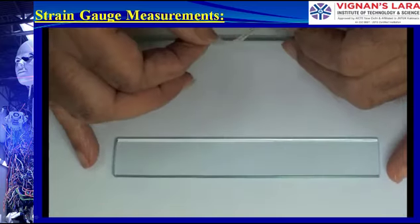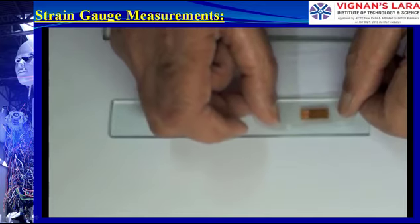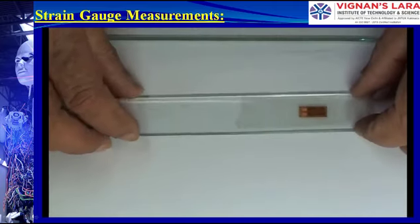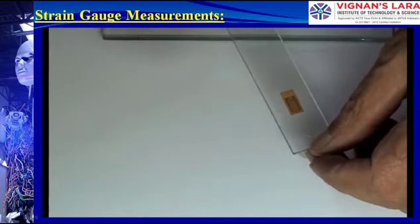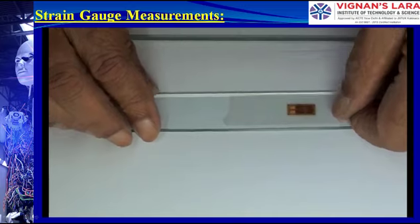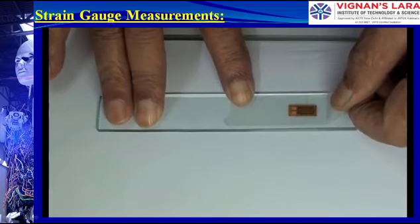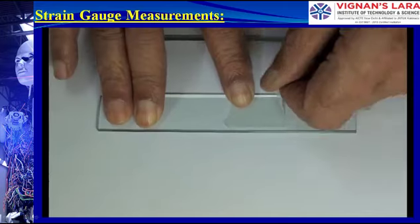It is positioned on the surface of the part, then one end is pressed down on the surface and the rest of the tape is pushed down gently. The gauge is inspected for correctness of the location. Then the tape is partially lifted off the surface at a shallow angle until the gauge is free. The tape is folded backwards to expose the bottom surface of the gauge.